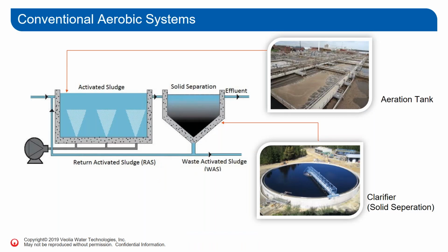If you look today, the great majority of the treatment process in the pulp and paper industry will be aerobic, and then we are looking into conventional systems such as aerobic stabilization basins with huge retention time, very big volumes, or you have conventional activated sludge plants such as the one you see in this slide here, where you have aeration basin followed by clarifiers to separate sludge and put it back to the aeration basin again.